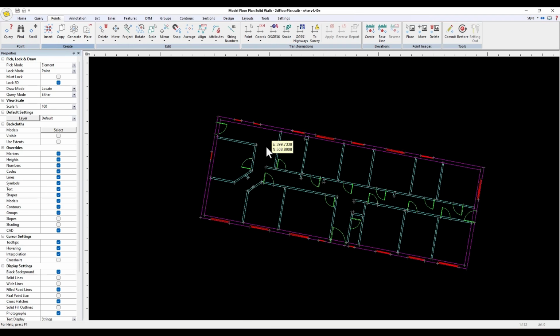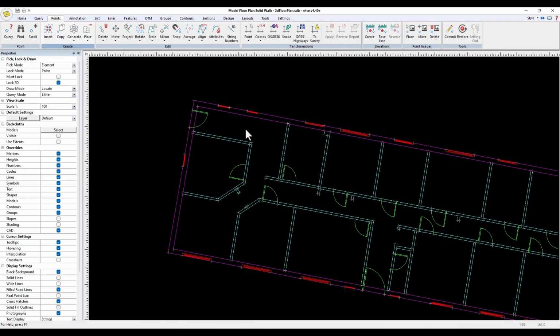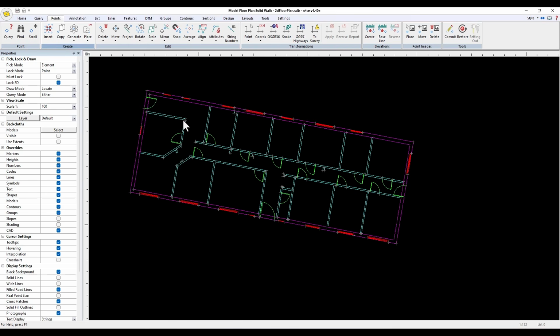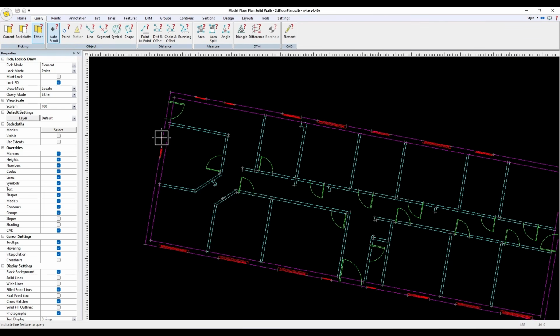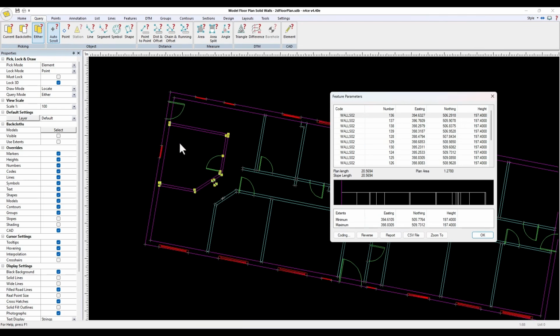The main change I had to make was for the walls, okay? So for the IFC file to correctly construct this geometry in 3D, you basically have to have an outer wall and an inner wall as your main construct for the start of the building, because the inner wall is going to cut itself into the outer wall to give you the essential shell of the building. And then everything else, all these internal walls, so if I was to go to query and get a query line, okay, that's a continuously closed feature. So that was the edits I had to make.